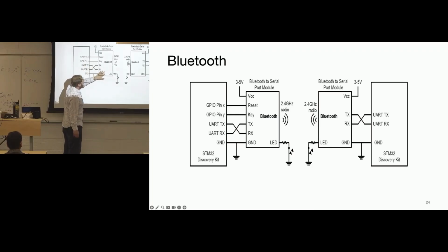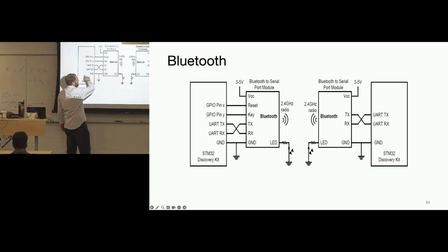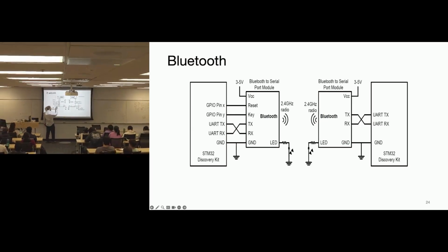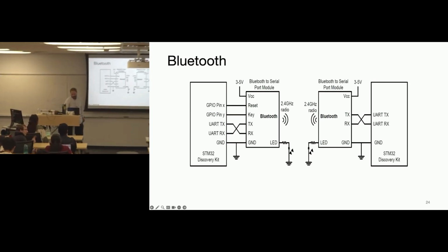These are for flow control for the Bluetooth specifically, but for UART here, remember you have the crossing structure, and they'll hook them up and say no data is going through. Well, if you have a USB powered thing and a battery powered thing over here, and you haven't connected the two ground pins together, then no current flows between them. Current always flows in a loop by definition, and right now you have no return path, so no current wants to go into this thing. You might get some random data, a little bit of signal, but it won't be robust. So when you're doing your labs, make sure you connect not only TX to RX and RX to TX, but also the ground wires. So at least 3 wires are going to be required.